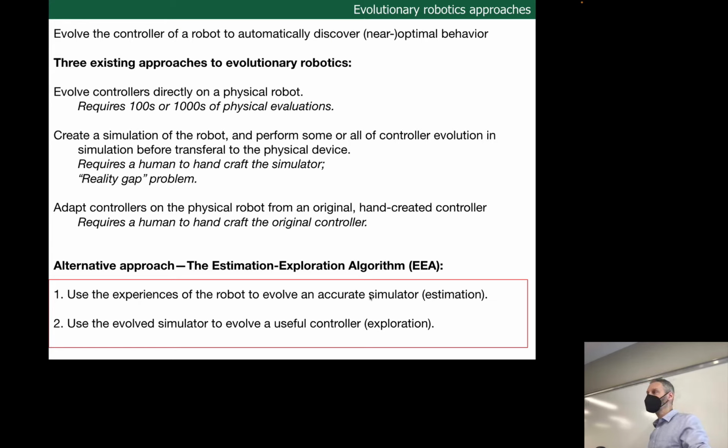What would be the fitness of a given simulator? We take a genome from this evolutionary algorithm, we pull out some numbers to set the friction parameters, we pull out some other numbers to guide how collision detection and resolution happens. We run the simulator. What's the fitness of the simulator? Is it how maybe we put sensors on the actual robot and measure how accurate the inputs and outputs are? Absolutely. So I think what you're describing and what we're going to talk about in a moment is not sim to real, but real to sim.